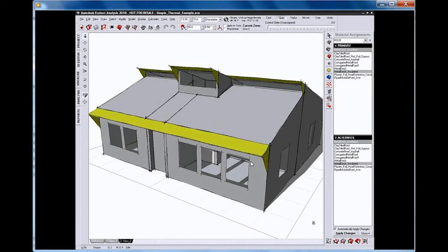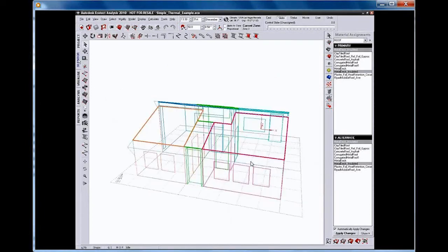Thermal analysis, so this is another example of my detailed demo earlier on. In this case, it's important for comfort levels and reducing energy levels, so we're going to investigate the roof construction as we did before, interrogate the material, and then possibly change the material based upon its properties, perform a passive gains analysis, and then interrogate the results.